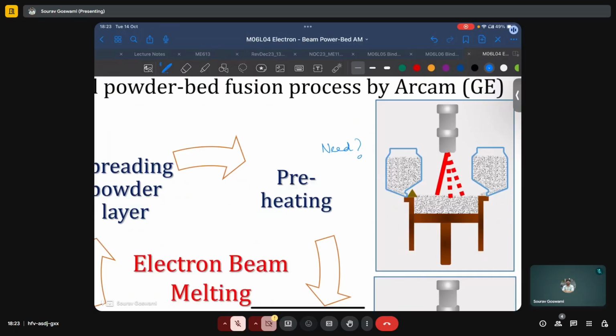Now, when we're starting to print, or the system has completely cooled down and we are about to print the next layer, the temperature achieved on the top of the powder layer will be at least the liquidus temperature and potentially even several hundred Kelvins higher. And typically these powder layers are of thickness of the order of 40 to 50 micrometers.